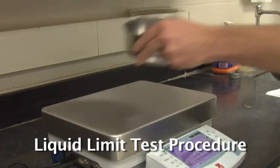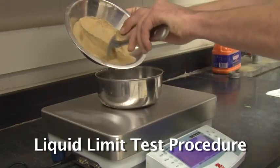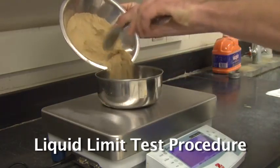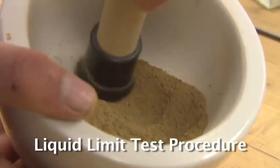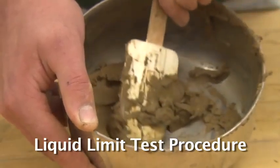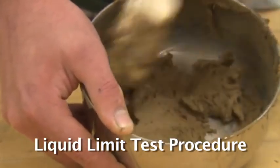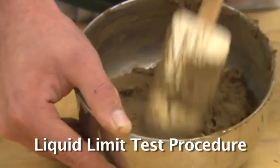To perform the liquid limit tests, weigh out about 300 grams of the provided soil. If the soil is clumpy, you can break it up in the mortar and pestle. Add water from the water bottle and mix the soil until it appears uniform and the surface looks creamy. A proper blending could take up to 20 minutes.